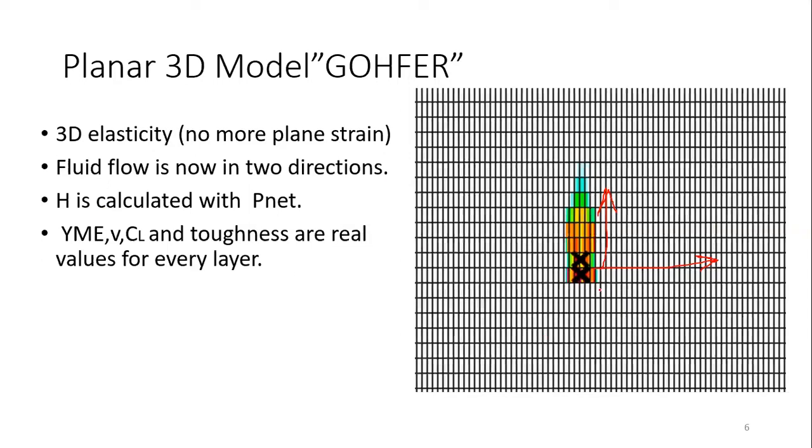So our mission today is to create these grids with GOHFER and apply hydraulic fracturing, and GOHFER will simulate the fluid flow from the wellbore into the reservoir, and once we distribute the properties in the grid, we can create a fracture which propagates in the reservoir.